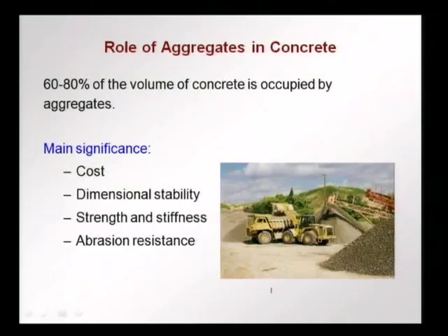The significance of using aggregates in concrete, first of all, is cost. Aggregates are cheaper than cement paste or cement, and therefore, it is better to have as much aggregates as possible in concrete. More importantly, we have dimensional stability and strength that comes from the aggregates. Dimensional stability meaning that there are no changes in volume as the concrete is hydrating as far as the aggregate is concerned. This gives rise to better dimensional stability in the concrete.